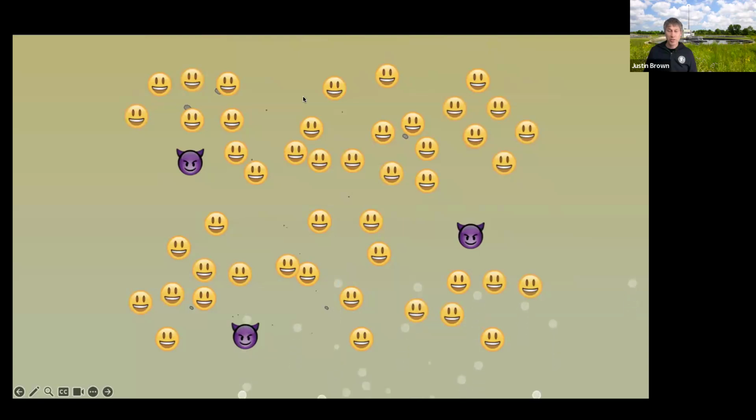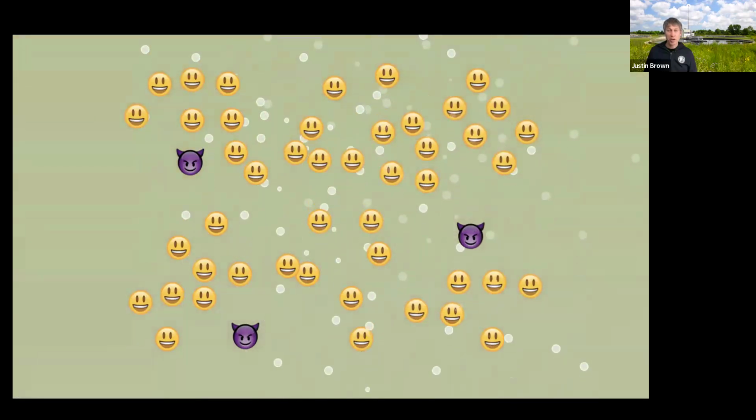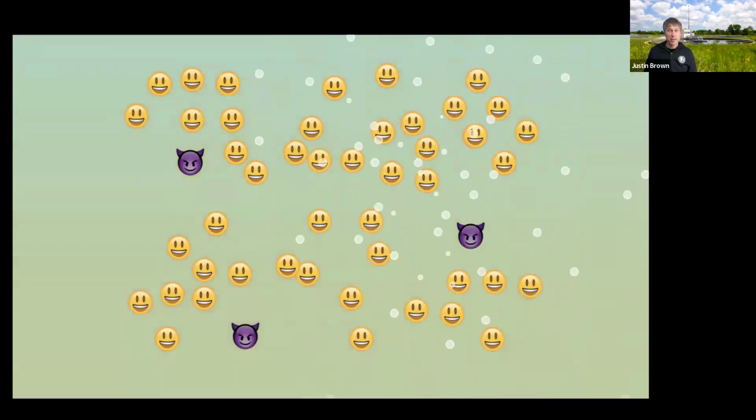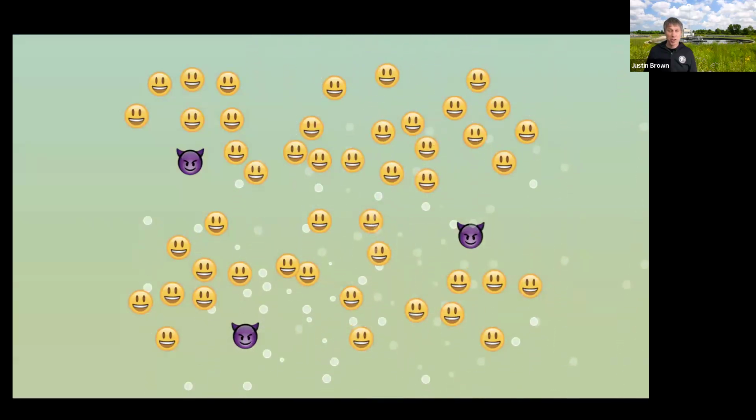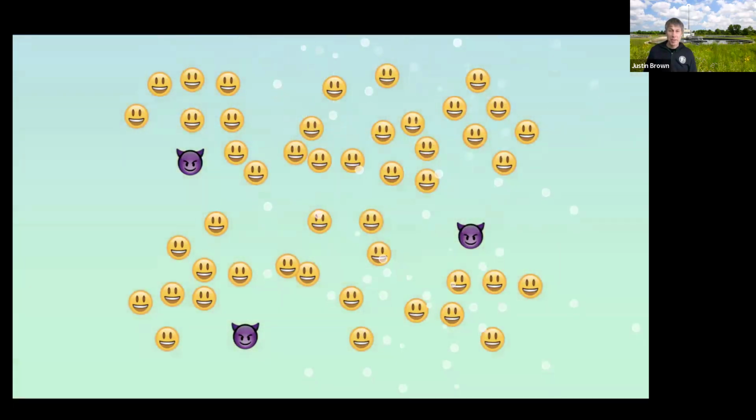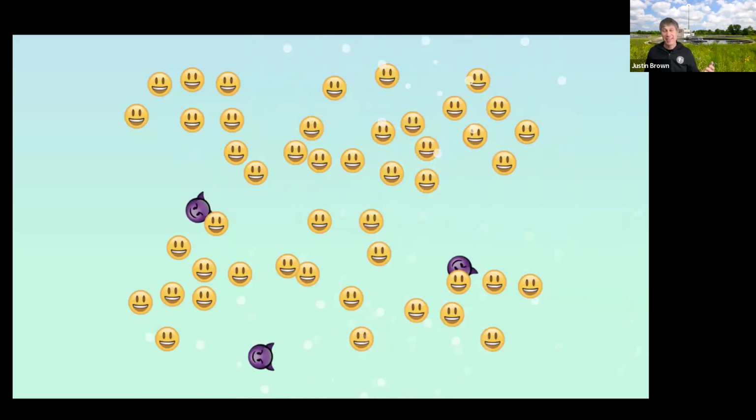Now we're flowing along through the aeration tank. Notice that the water is getting cleaner. The good guys are getting more numerous here. The pathogens or germs tend to be anaerobic organisms, meaning they thrive in the absence of oxygen, and in some cases oxygen is actually toxic to them. So they actually get outcompeted for food and they tend to die off. Our microbiology lab pulls samples and we confirm that this is occurring.